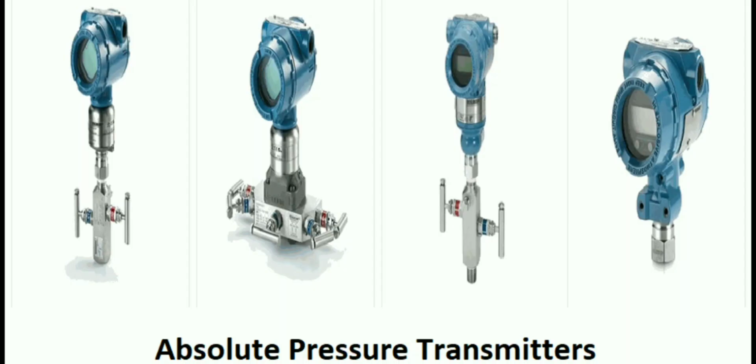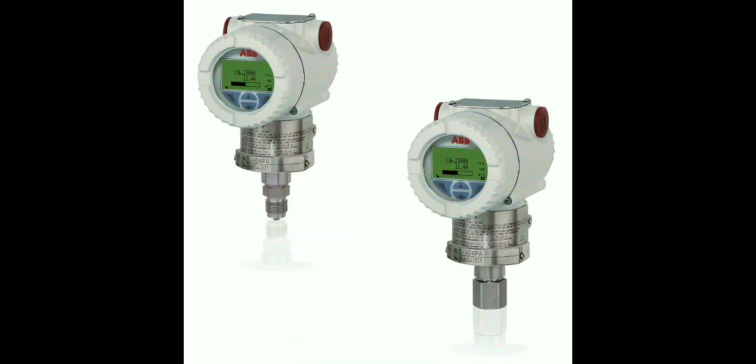Let's look at the applications of an absolute pressure transmitter. Absolute pressure transmitters are crucial in applications where pressure is measured in a vacuum or at a very low pressure. It is used in applications where altitude measurement is critical, such as avionics and aerospace systems. Absolute pressure measurements are used in meteorology to measure barometric pressure accurately. It is used in laboratories where precise pressure measurements are required without variation caused by atmospheric pressure change.